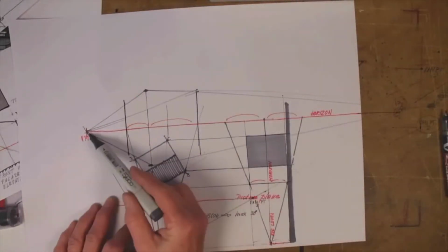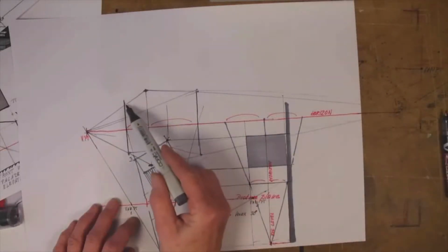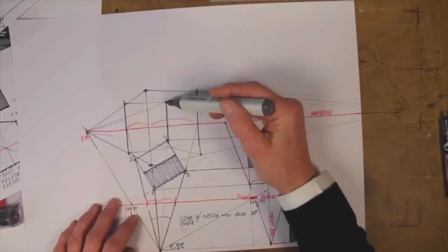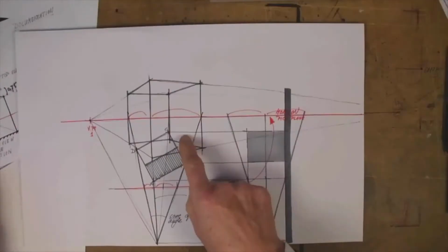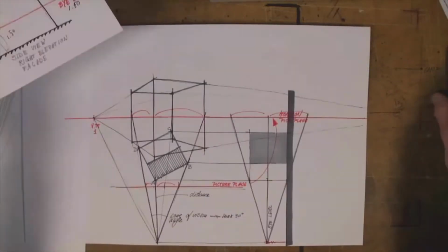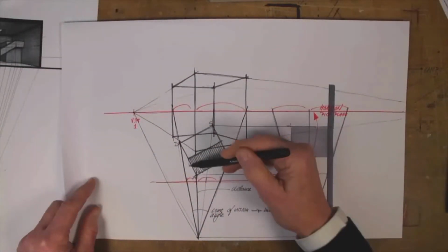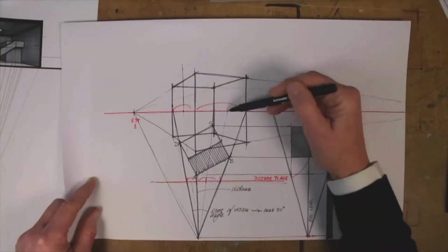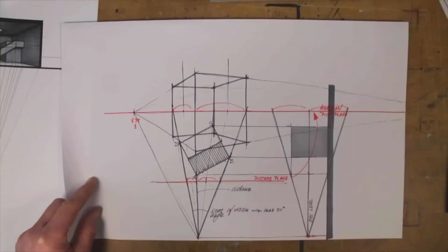Now also draw the back of the cube so that it becomes transparent. This could be necessary if you need to make more construction. Don't forget to make the rooftop. I can place it on the right position in the perspective, making the rays from my eye to the middle of the top view. The height of the roof is 1/4 of the height of the cube.